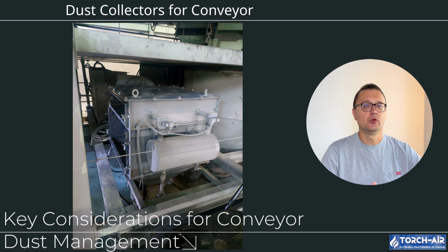B. Choosing the right method for your operation. The type of dust control method you choose will depend on your material, dust load, and conveyor type. For heavy-duty operations, you might need a more robust system like the Bora filter, while simpler conveyor setups might benefit from basic covers or water spraying.